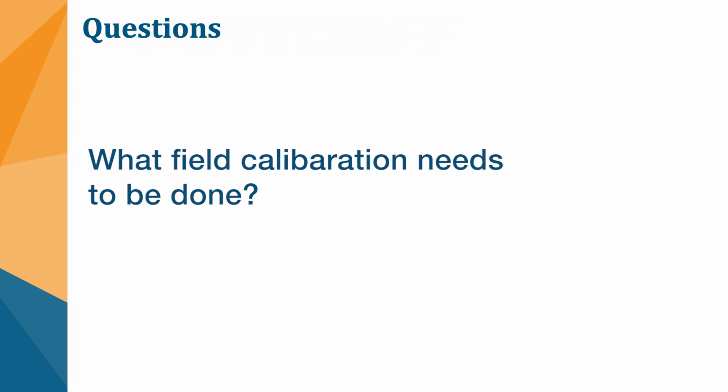There's a procedure for the unit to self-calibrate if you're seeing errors in the field, but typically that's not needed. The only time I've seen that needed is if there was something either wrong with the unit or something changed along the way. Because of the ordering process, there'll be a system CFM or a feet per minute, and then the duct size to calibrate it. So there's really no field calibration needed for these. They're typically set up from the factory that way.